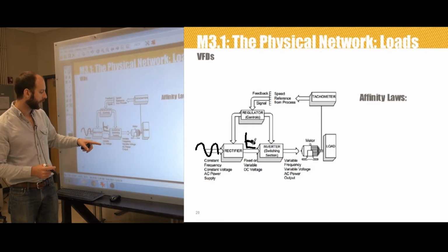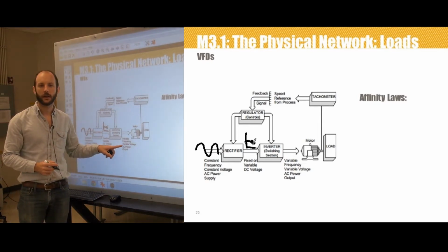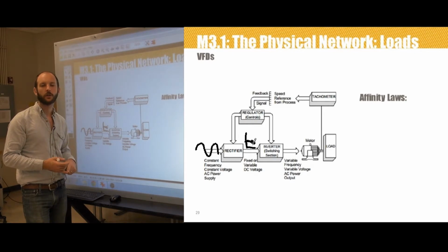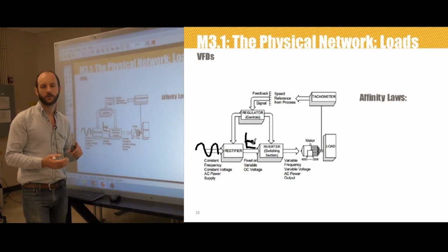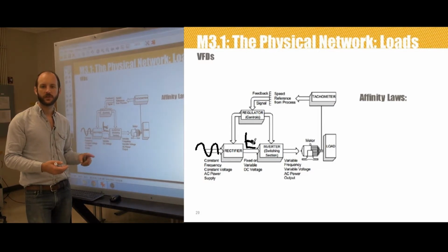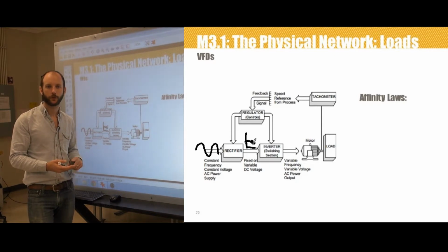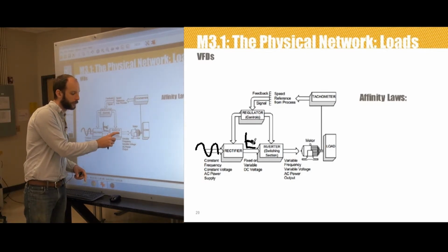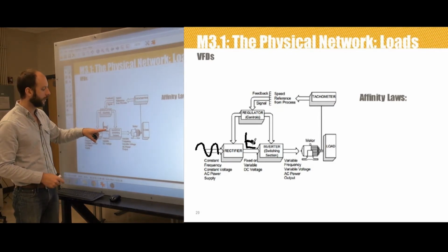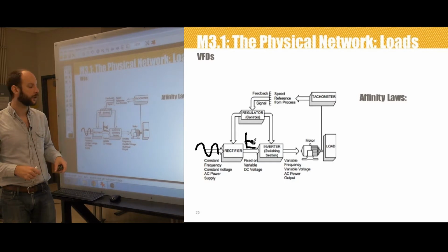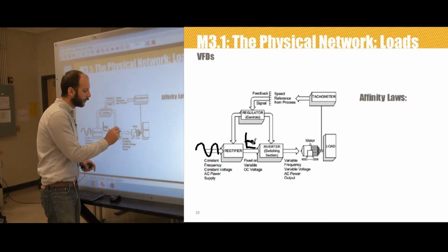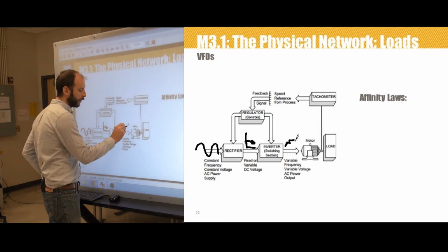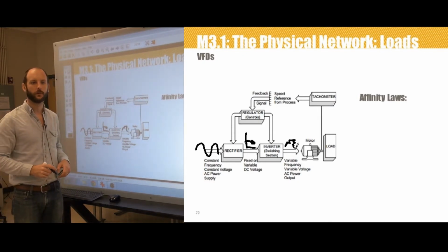The inverter then takes the fixed DC voltage and creates an output waveform of a different frequency. It creates a different sine wave. It does this using devices called thyristors or silicon-controlled rectifiers, and what they do is they switch the DC power on and off to produce a controllable AC power output at the desired frequency and the desired voltage. A lot of times you see this in parentheses, it's called the switching section. What this is doing is just switching the DC voltage that's supplied to the motor on and off really fast to recreate an AC sine wave. Although it's called an AC sine wave, if you look at it closely, it has some kind of digital nature to it. It almost looks binary if you look at it in a close enough resolution.